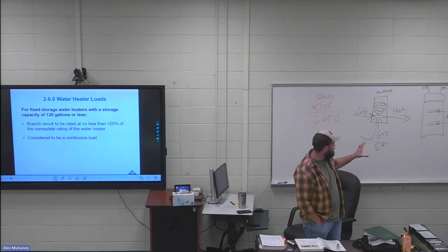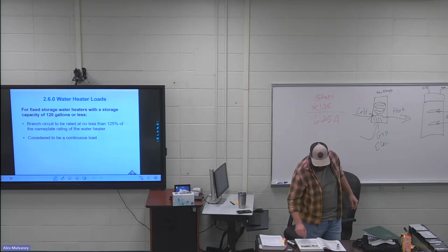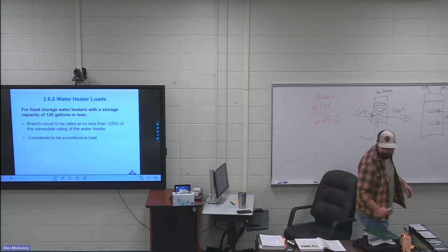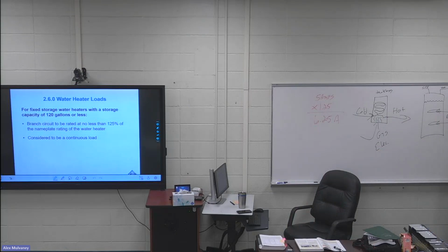So if you have an electric storage type water heater and the nameplate rating is, say, 30 amps, what do I have to take that 30 amps at? 125%.